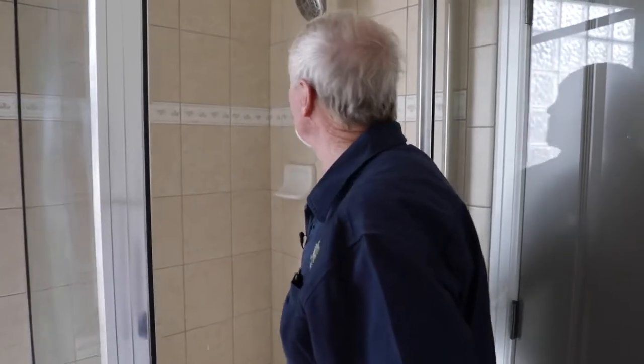Very good. One thing you can also do is check the temperature of the water coming out of the water heater. If the temperature coming out of the water heater is under 120 degrees, you know you're going to be good at all your fixtures in the house. And you're out of the gate going to be good there.